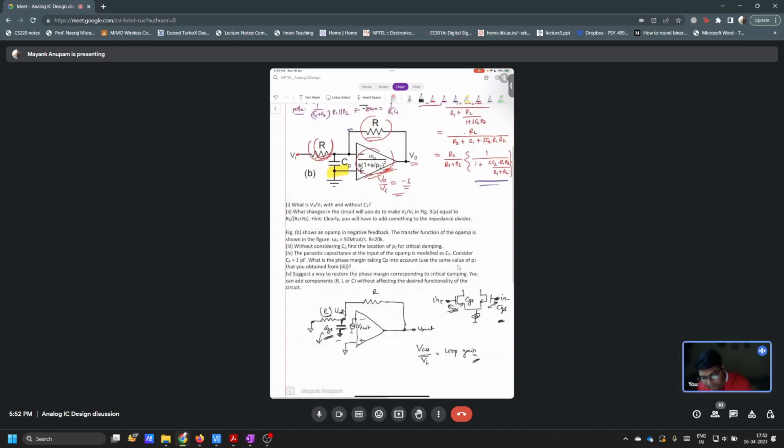You only said, right, that this resistance here will start to load this particular op amp, isn't it? Yes, sir. So you cannot go on decreasing it. It is true, you can decrease it, but you cannot go on decreasing it. Let's say we have decreased it to the least value that we can tolerate, but even then the loop is not stable.